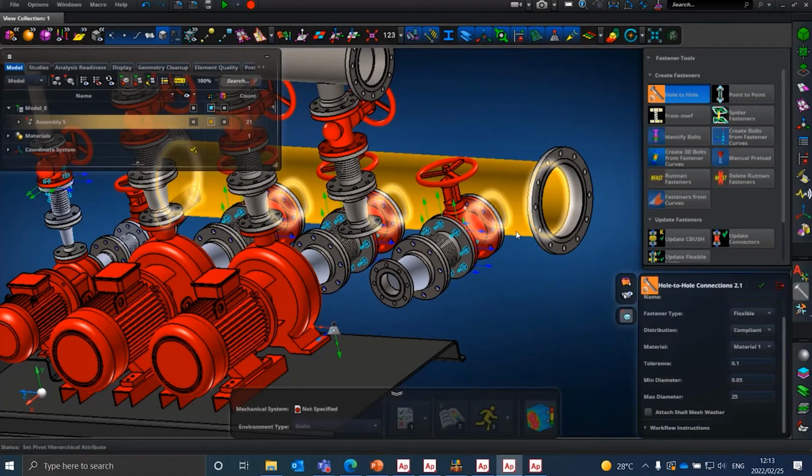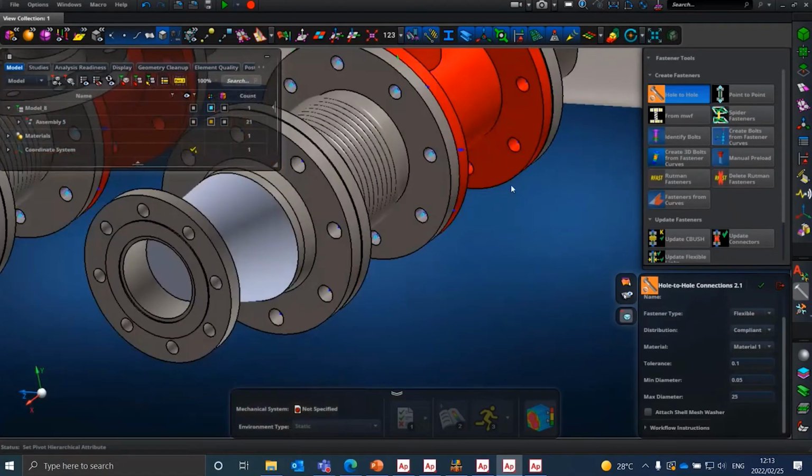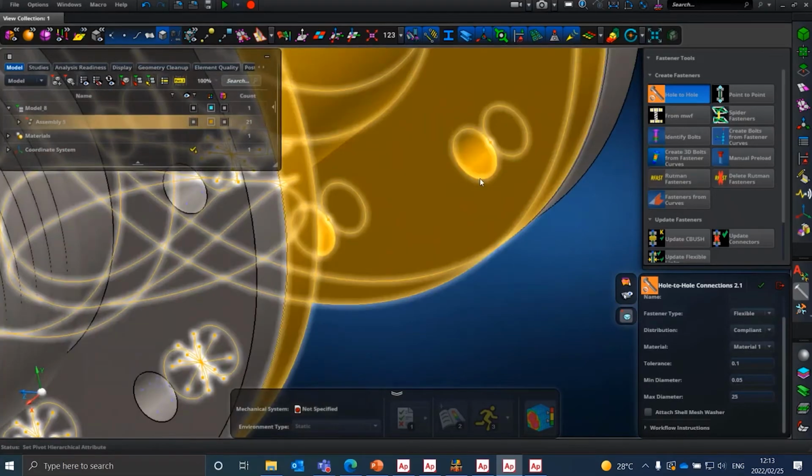The other thing that I should also mention is if you use surfaces to represent your holes, you should make sure that there's only one vertex representing that hole. Often when you import CAD, they tend to represent it with two vertices. So it will typically have one vertex at the bottom and one vertex at the top.